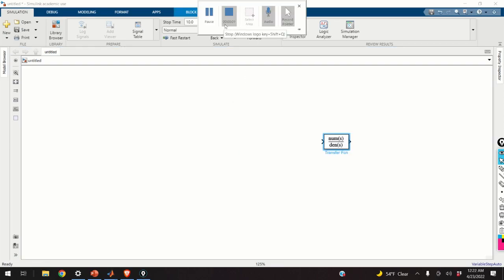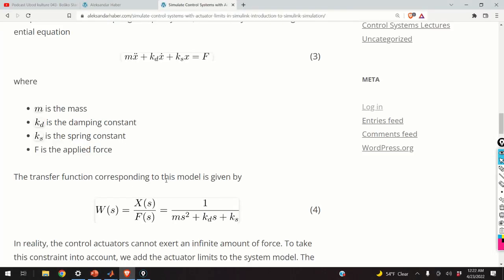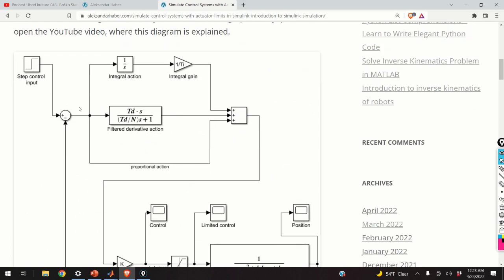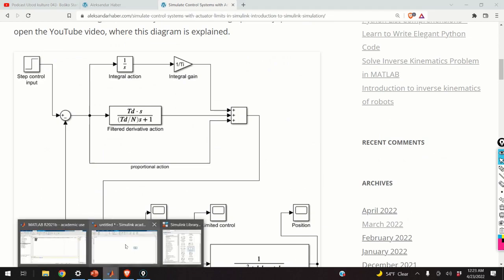The next step is to add a feedback loop and to add our reference input. To add the feedback loop, we will need an element that will subtract two signals. So if you go back to the original Simulink model, we need to introduce this subtraction module. How to do that?